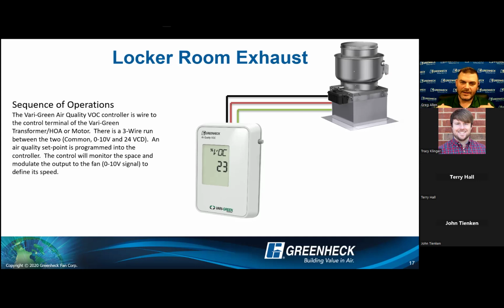It can see what the level or the quality of the air is in that space. And it takes your input, your set point of what level of air quality you want to maintain. And the worse it gets in that environment, the higher the fan's going to run.